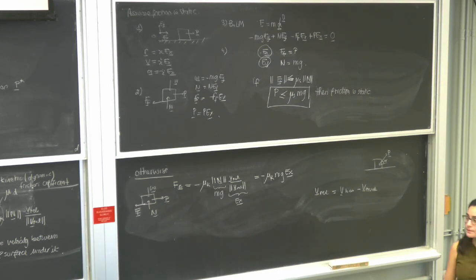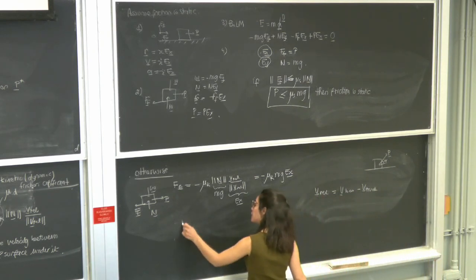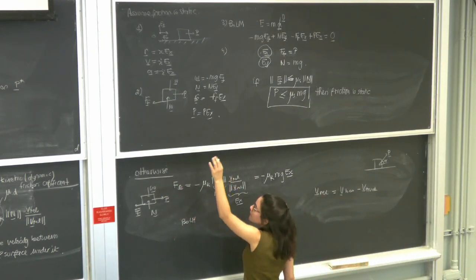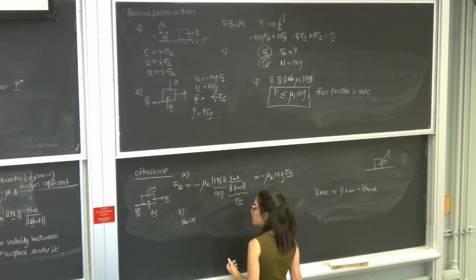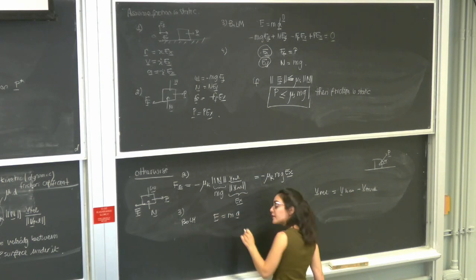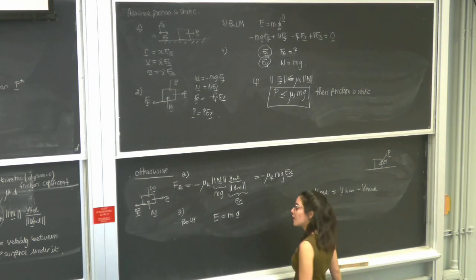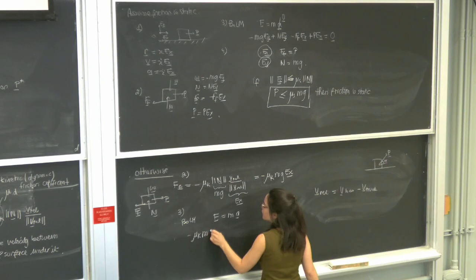Yes, exactly, the balance law. So the balance of linear momentum. So it's kind of like here where step 1 is the same, step 2, a slightly different expression for the friction force. Step 3, the balance of linear momentum, F is equal to ma. Is A equal to 0 in this case? No, A is an unknown, the acceleration of the block, which we want to find. So we'll have the minus mu k mg Ex